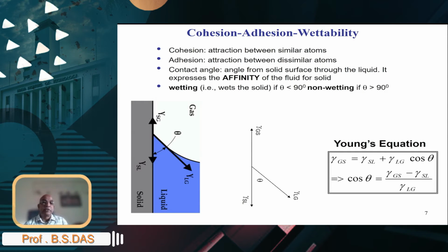And as you can see in this figure here, these three forces, because of the interfaces between solid-gas, solid-liquid, and liquid-gas, make the water surface curve, and the angle measured from the solid through the liquid to the liquid-gas interface is called the contact angle.